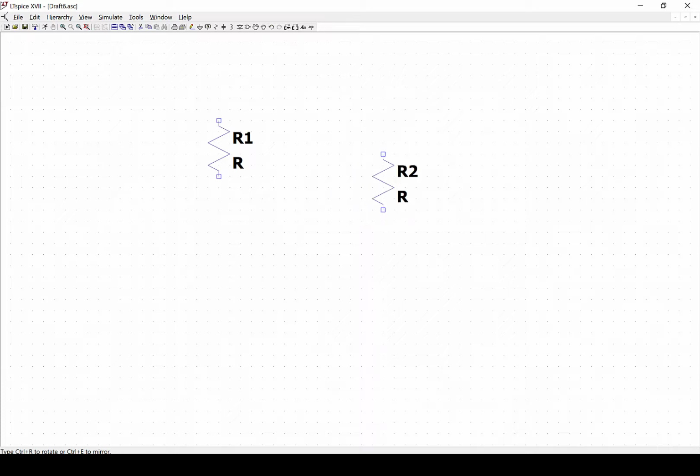Once I click with the mouse, a second resistor appears. Now, what I can decide is whether to click on the escape key, so it disappears and I can start again. Or the other opportunity would have been to add the second resistor at a specific position in my circuit. Say we want to add a second resistor. If it is a network of resistors that is biasing, for instance, a bipolar transistor, I can add a resistor here, R2, and then I can decide on adding another resistor here, R3, and adding another resistor here.